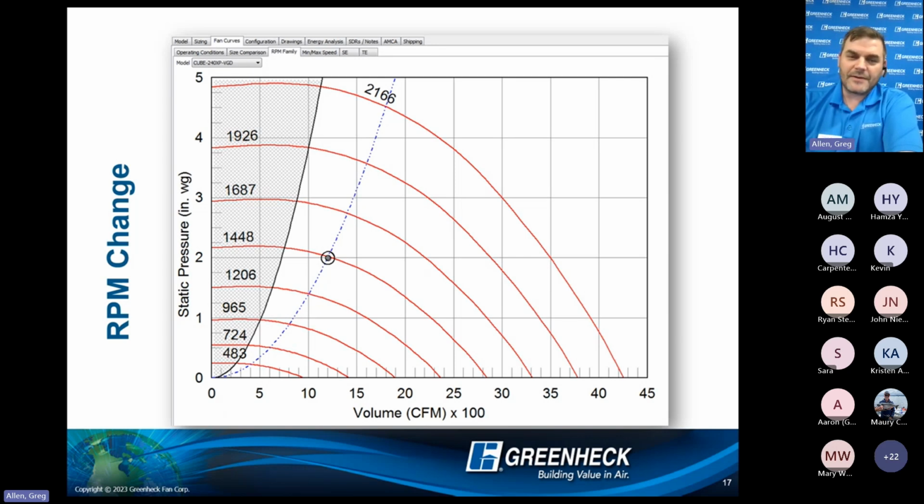You're going to have higher CFM in that same point, or lower. But this gives you an idea of, okay, what RPM do I need this fan to operate at? Say I have 2 points of operation, or I'm trying to extend the life of this fan into a secondary application, right? So this is where the value of an RPM change curve would be.